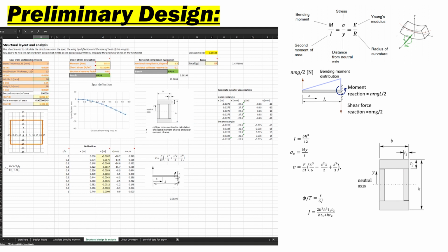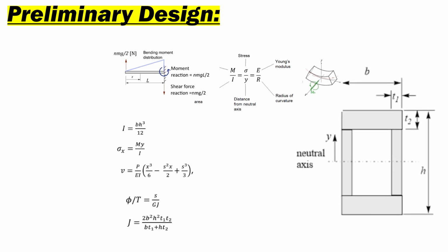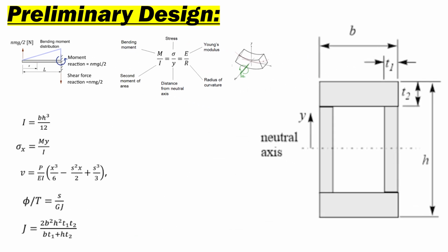Additionally, the equation for deflection of the tip was again inversely proportional to the second moment of area. As many of the variables in the equation were determined by the specification already, this meant that the compliance of our spar depended largely on the geometry of the beam. By inputting the new equations for deflection, torsion, and maximum shear in terms of the width, height, and thickness of the spar, we could find the theoretically optimal configuration that minimized all 3 functions.